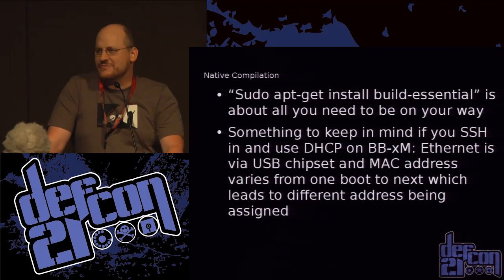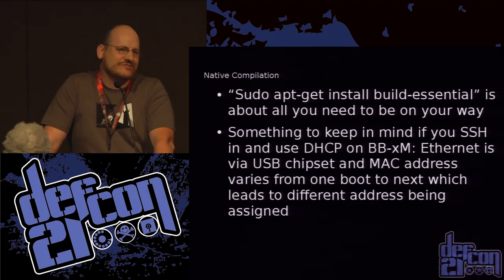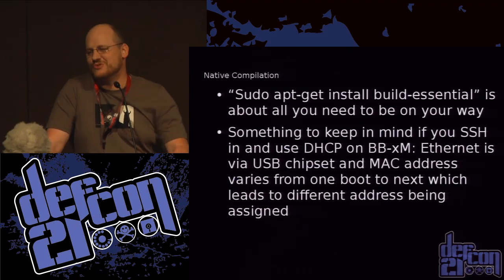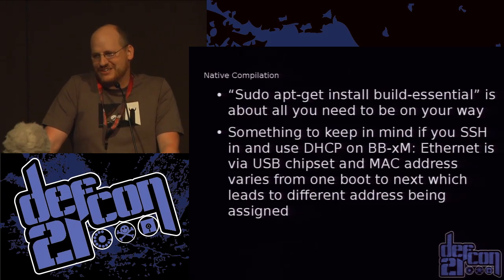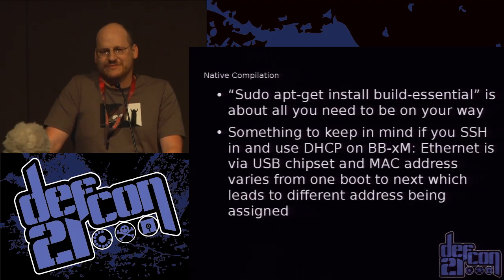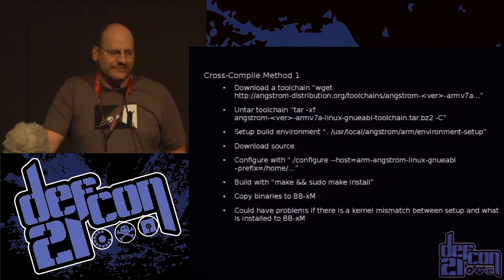Right? Something to keep in mind, if you happen to be using the BeagleBoard XM, be aware that if you're SSHing in there and you're using DHCP, every time you reboot the machine, it gives you a new MAC address, so you tend to get a new IP address. So if you're wondering, hey, why did that move yesterday? Well, just don't ever turn it off. You'll be fine.